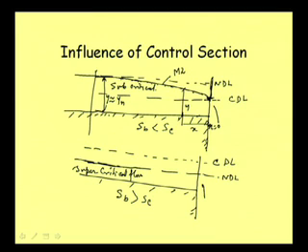So, what will happen? The supercritical flow will be moving straight this way, and then it is coming up to this point, and then it is dropping like this. So, there will not be any gradually varied flow forming at the upstream point here. At the upstream point, we will not be getting any gradually varied flow if the supercritical flow is forming here, and that will continue straight and it will fall like that.